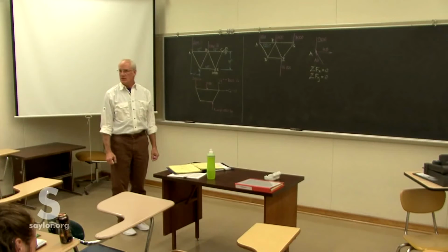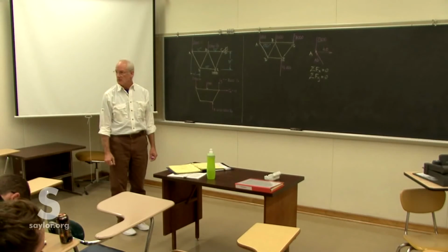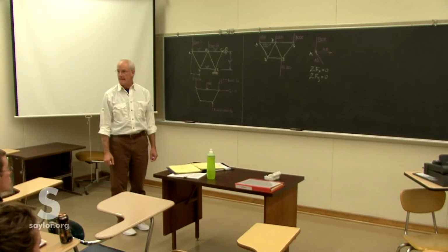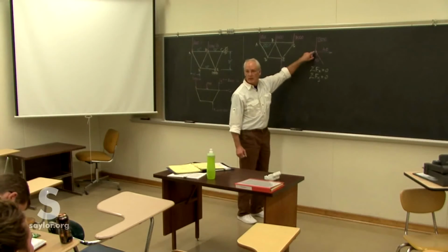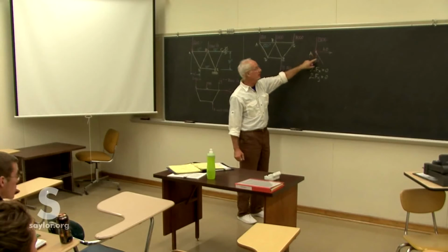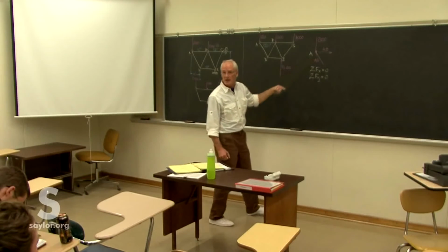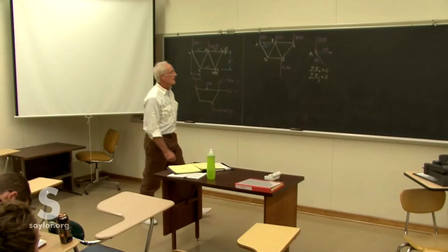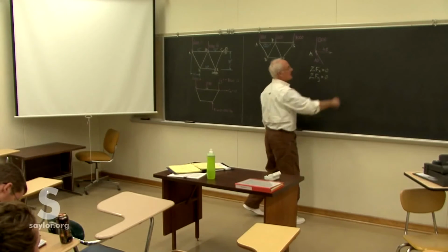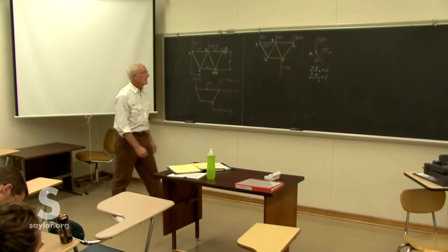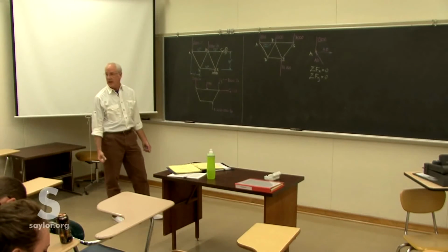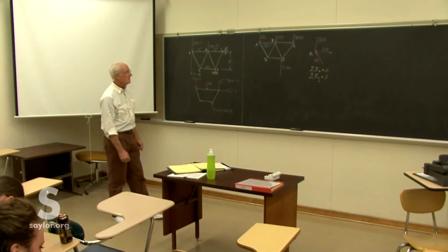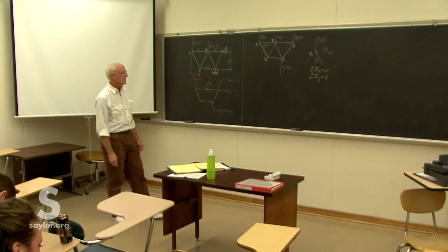What about using a moment equation? No need, because we only have point A. They'd all be zero. Well, there is no moment in this little sub-problem we have here. All forces go through the same point. None of them exert any moment. It's no use going over to some other point because that just complicates things. I guess we could do that. We can sum the moment about any point, even if it's somewhere else. But it's sufficient to do this, and we don't need to do anything more.